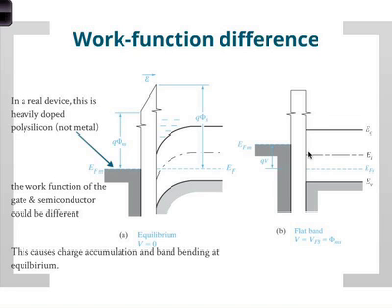Okay? From there, you want to go further to get a threshold voltage, or go back, you'll get accumulation. So instead of being 0 volts before, now we have biased that to some flat band voltage. Okay? That's a real device. And we have to account for that.